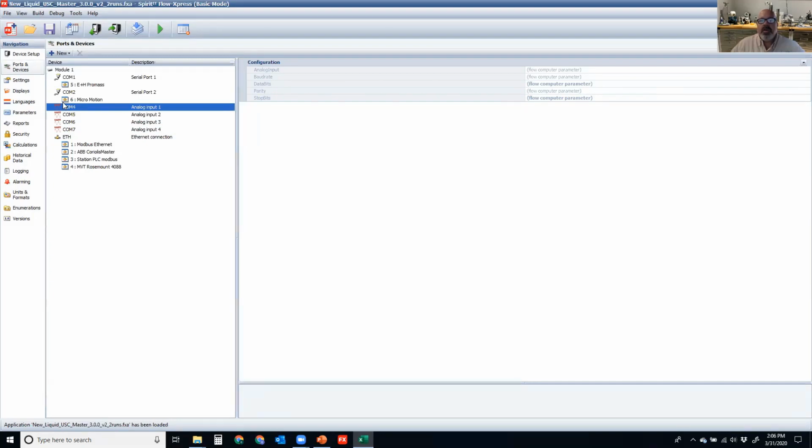device, or each analog, can have up to 16 HART devices on there. So we can multi-drop up to 16 HART devices, 16 transmitters or other HART devices on just one analog loop. So that makes it where a single module can handle up to 64 different HART devices.